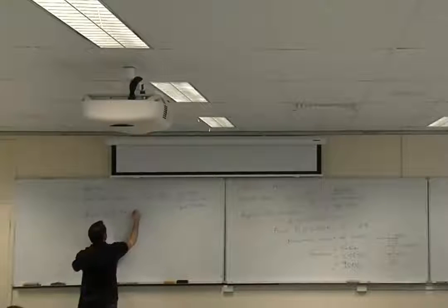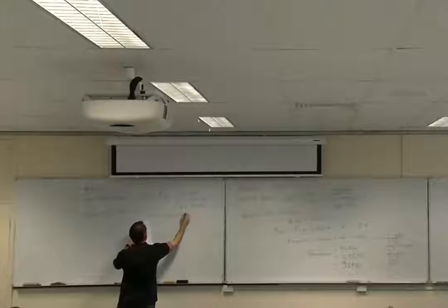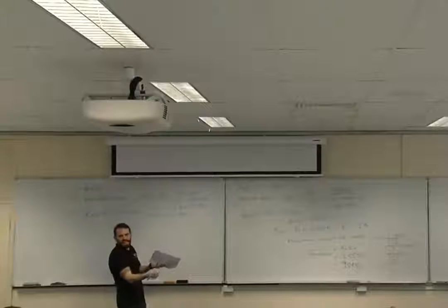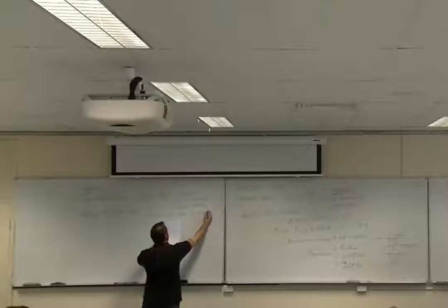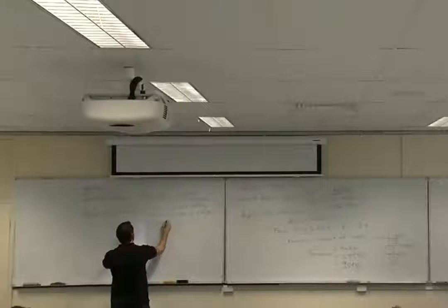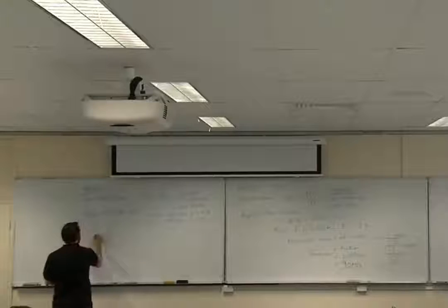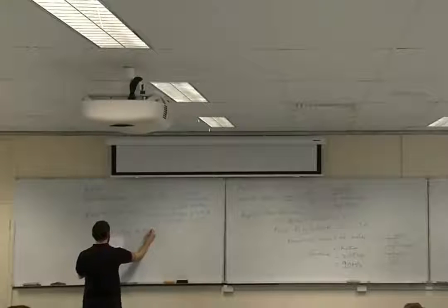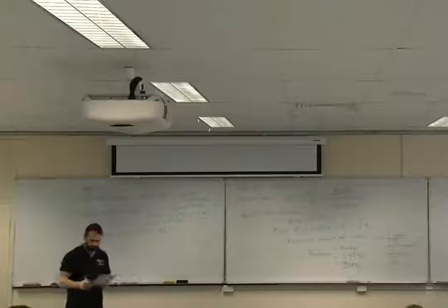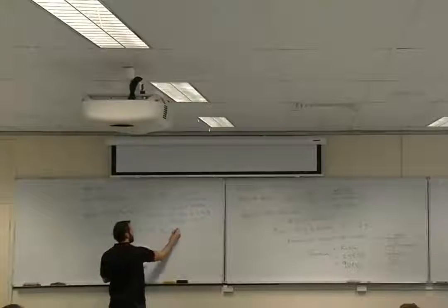Then we can have our ratios for KT calc. H on h equals 100 on 70. I'm using millimeters here because it's a ratio, so I can. It's not because I've made a mistake. That's 1.43, and the other ratio is little r on little h, 15 on 70, 0.21. So from figure 4.39b, KT equals, what do we get? 1.95, somewhere around it. Let's use 1.95, that's fine.